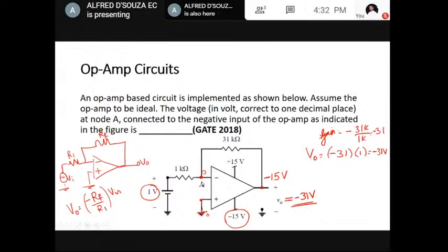We will have to calculate. So it is not 0. So how do we calculate? We shall apply KCL at this node. Current going into this particular terminal is negligible because the op amp is ideal. It is 0. So we can assume a current is flowing like this, I1. You can assume current flowing like this, I2. So what we can do is take I1 is equal to minus I2. You can assume it to be in any direction, but the appropriate sign must be considered.